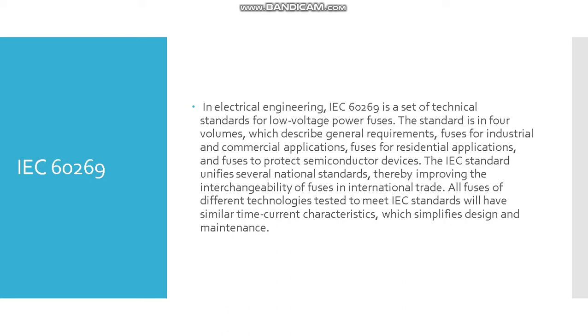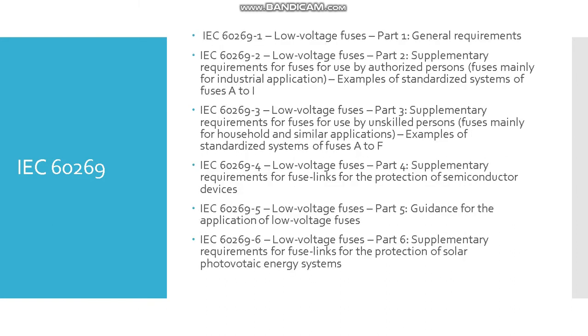So the IEC standard unifies several national standards, thereby improving the interchangeability of fuses in international trade. All fuses, of different technologies, tested to meet the IEC standards will have similar time current characteristics, which simplifies the design and maintenance. So here are the parts of the IEC 60269.